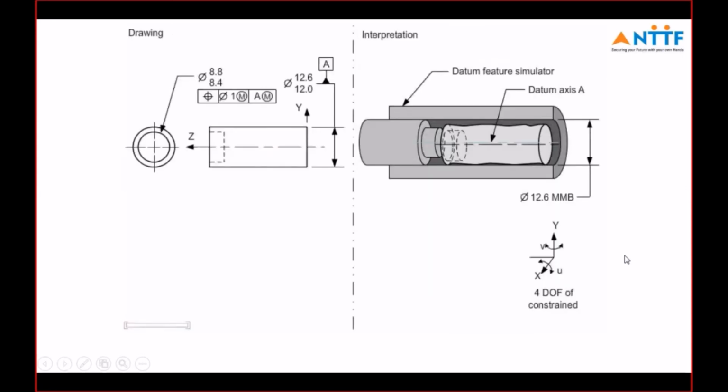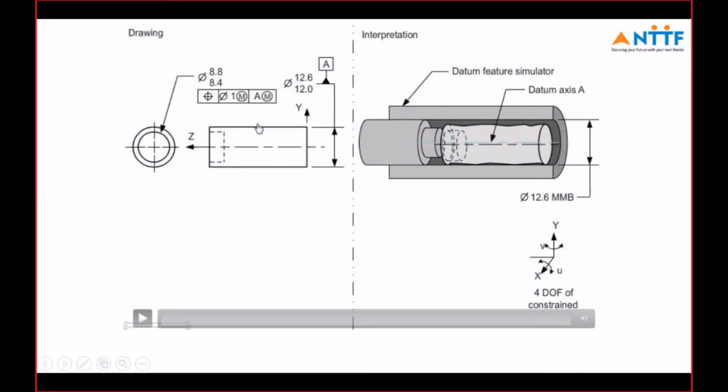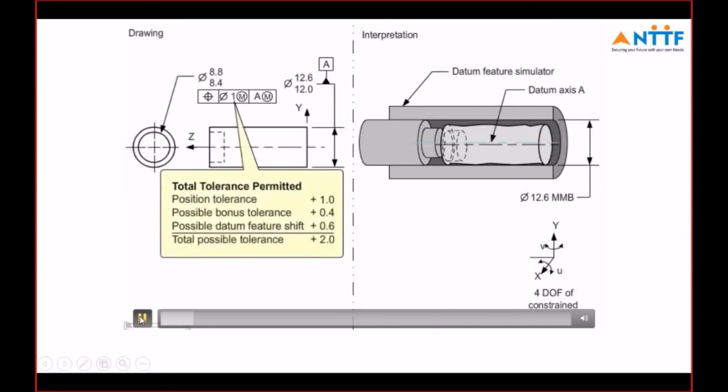There is another example which I would like to show you, a position tolerance. So this pin has a counterbore, and this has to be checked with reference to the outside diameter. There is a meaning if there is a modifier in the tolerance zone, and there is another meaning when the same modifier is used in the datum portion. So taking this requirement, and making a hard gauge and checking the counterbore with the plug gauge, see how it works?